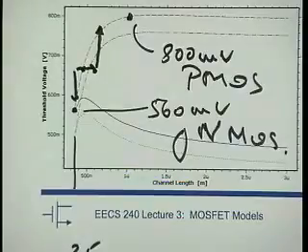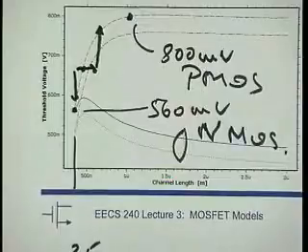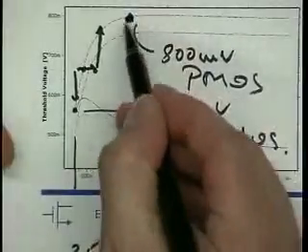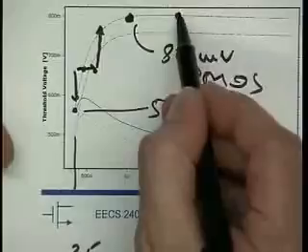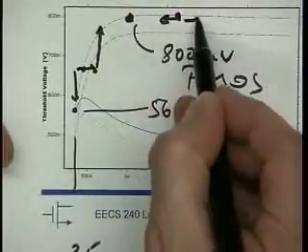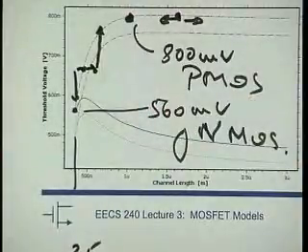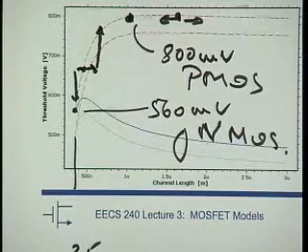Well, yeah, it does, right? So if I depend on good threshold voltage matching, I've got to use a 1 micron device or 1.5 micron device. Now a little variation doesn't result in a significant change in threshold voltage. Okay.